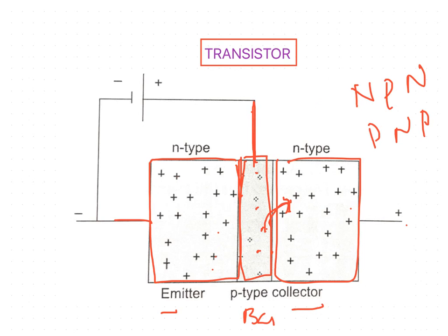Thus, a current fed into the base renders the transistor capable of conducting current, and small variations in this base current cause greater variations of current flowing across the transistor. In this respect, the current fed into the base has an effect comparable to that of a positive charge applied to the grid of a triode valve.